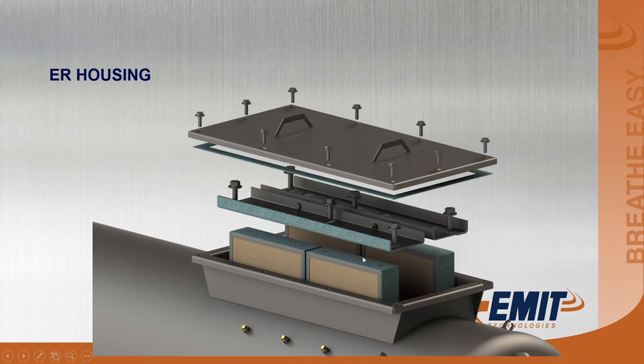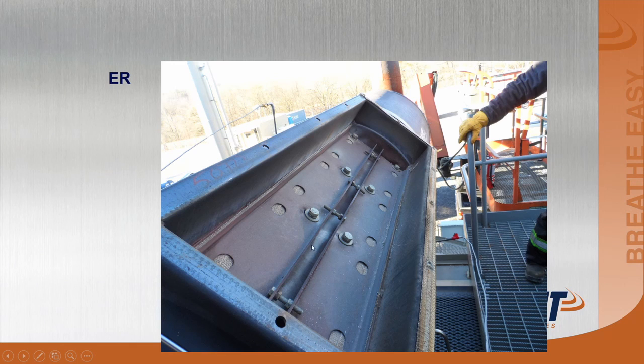Again, very important to have the gaskets in place and sealing correctly, and to have these forcing screws pushing these two plates apart and sealing on opposite bulkheads. Okay, so this is what a real one looks like out in the field. You can see the gasket down each side. You don't worry too much about it passing on the top from the first pass, because you have to go through the second pass anyway. There's no way out of this chamber without going through the second pass. Again, extremely low numbers.